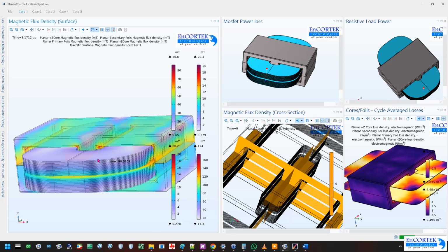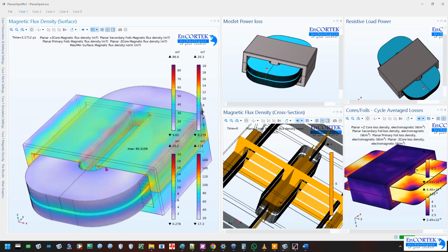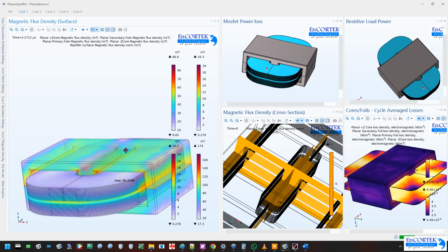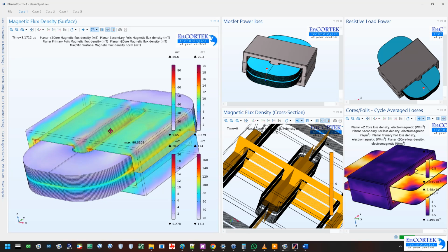All those things, for the mechanical engineering, I could look at when building the final-stage transformer like this or in the other configuration. When I'm doing that, I see in the simulation results that I will have to manufacture the two configurations and do real-time bench tests. For those bench tests, I will have to use infrared cameras and put sensors inside the transformer itself to be able to measure the temperature.